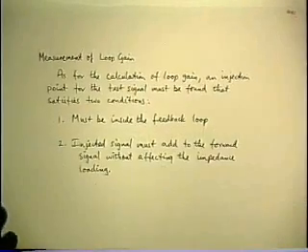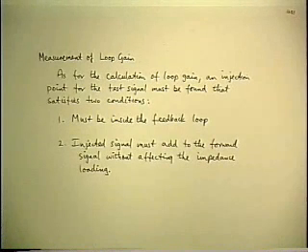Right, now we start the last major topic. I think we're assured now that the loop gain is the central parameter. Everything depends on loop gain. From it, you can calculate everything to do with the closed loop properties, including input and output impedances and stability. The only other thing you need is the G infinity, but that's the specification, and that's almost trivial because that's the starting point. Everything else depends on T.